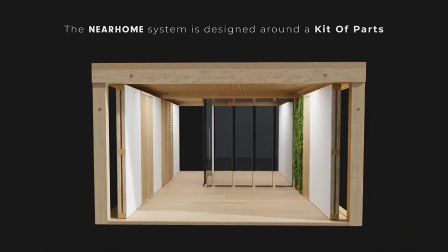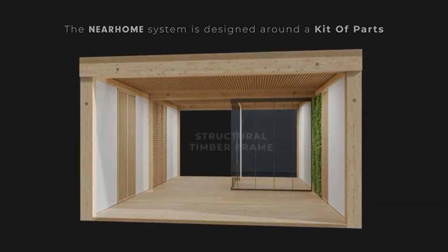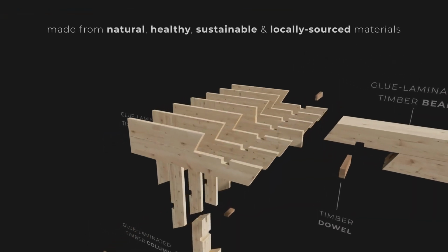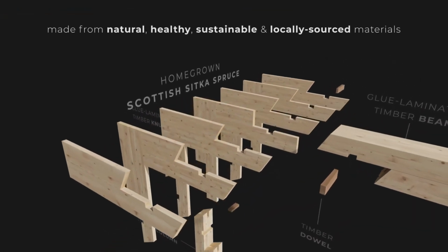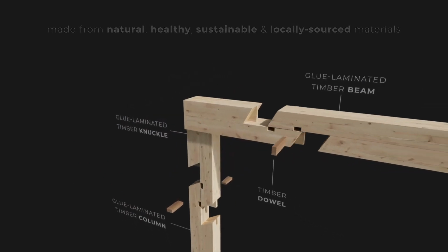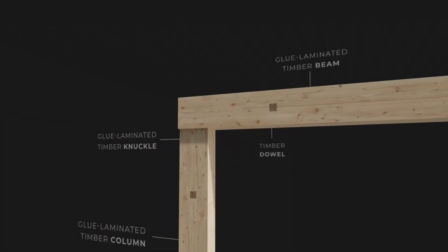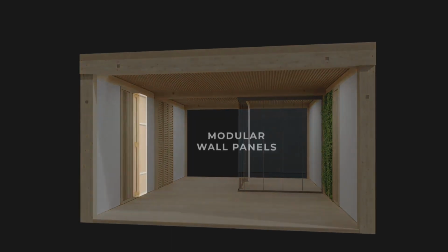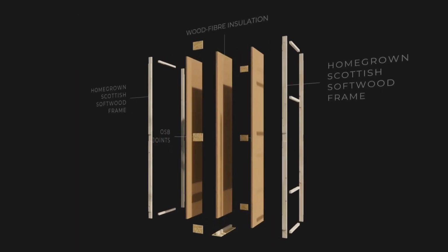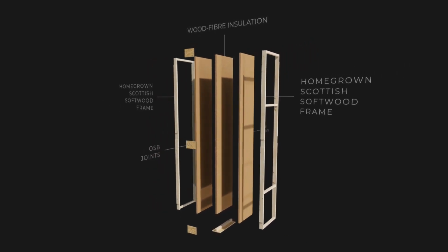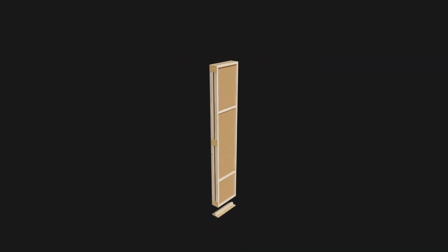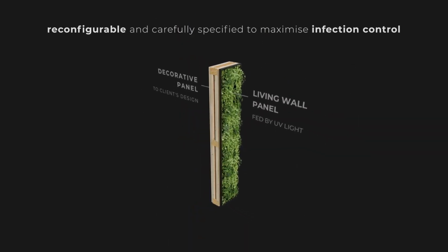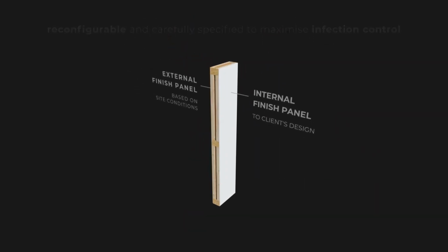Made it in timber, and it's a portalized frame, so it's got moment resistance connections for all the engineers here. It's made up of glue laminated, and you can see the joints are a bit like a finger joint, how it was made, or cross laminated timber for the specialists. Now, the design had to be that the racking panels in between could be anything they want. Bare minimum, a timber frame wall, or multiple panels, and you can finish any old way that it wants.